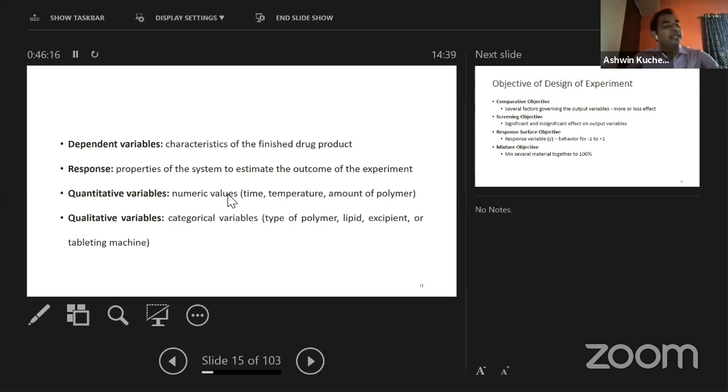And so in design of experiment, when you use different softwares, you can type there numerically as well as categorically, like high, low, medium, or fast, slow. When you go for RMG, there are two different options, low and high. There we don't have any RPM, so there you have to set as low and high for these RMGs, rapid mixing granulators during wet granulations.